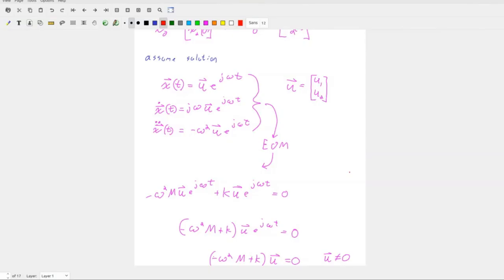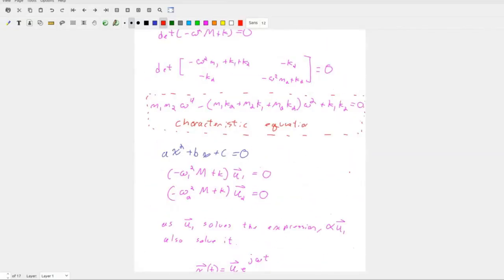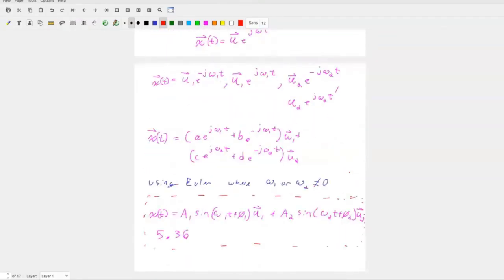From my characteristic equation, I'm now at my omega to the fourth terms, right? I can solve my characteristic equation using the quadratic formula, right? So then I have two solutions, positive and negative. And once I get back the solutions, positive and negative, I get something that looks like Euler's expression, and I can use Euler's to get back into a real solution.